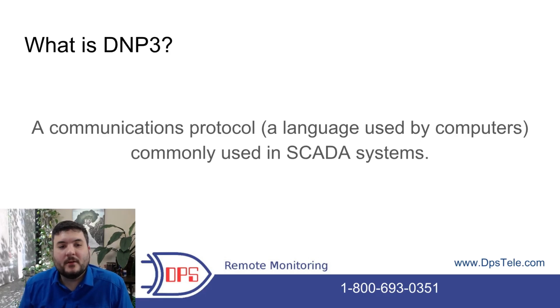So whereas something like SNMP might be more of a telecom protocol, you'll see DNP3 in a SCADA environment, which could be a utility, wastewater, a water district, could be manufacturing, a lot of different areas, but SCADA has a general meaning within certain industries, and that's more commonly where DNP3 will be.